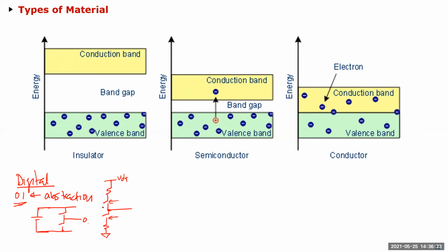So that's the idea. Now, obviously, you cannot do this with a passive device. A passive device is just a resistor or a cap. What you want is a 3-terminal device, basically a controllable resistor. So you want somewhere you can control with a voltage, and that switches this resistor between VDD or ground to this node. That's what you're looking for, right?